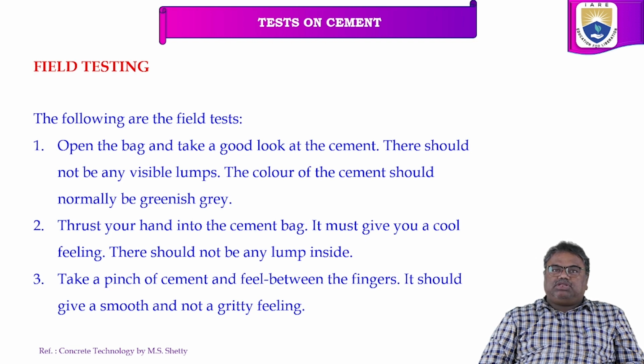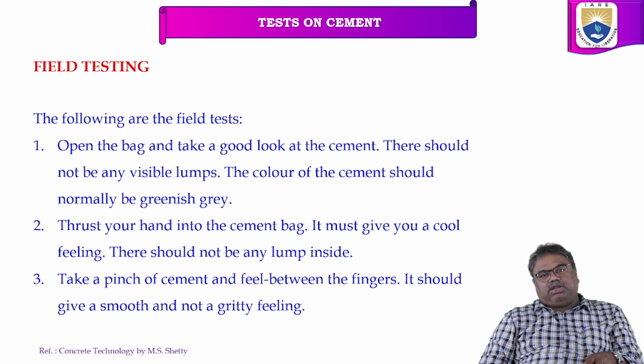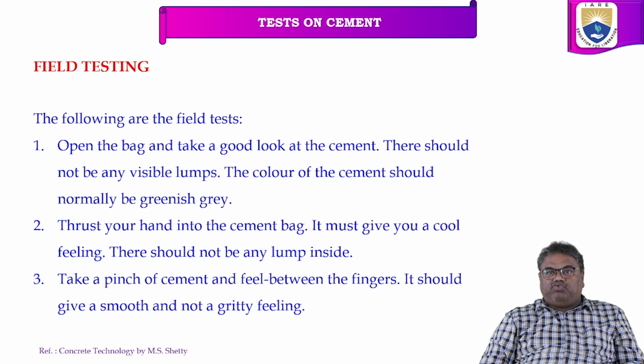In the first step, we see just outside whether any lumps are there. Once you dip your hand into the cement, it should have a cool feeling, and there should not be any lumps inside. So this is the second test. And the third one: take a pinch of cement.